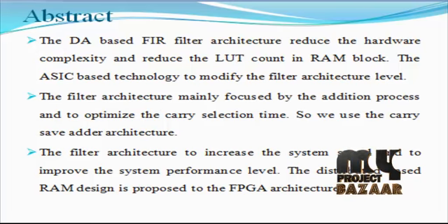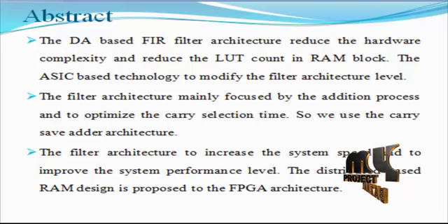Reconfigurable finite impulse response filters, whose filter coefficients dynamically change during runtime, play an important role in software defined radio systems, multi-channel filters and digital up-down converters. However, the well-known multiple constant multiplication based technique, which is widely used for the implementation of FIR filters, cannot be used when the filter coefficients dynamically change.